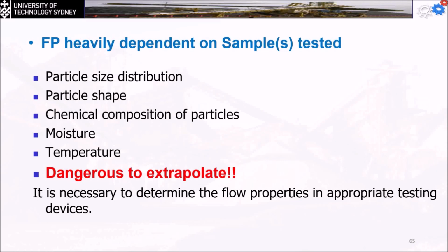Even the density of the material is going to be quite different on the second day from the first day and the third day, because it's under pressure, so the density is always going to increase while it's stored in the silo. You are going to have an equation for that, and you have to do some calculation for your solution. So the internal strength, the cohesion, the wall friction, and the time consolidation are going to be used to establish the flow properties, or the flowability, of the bulk material.